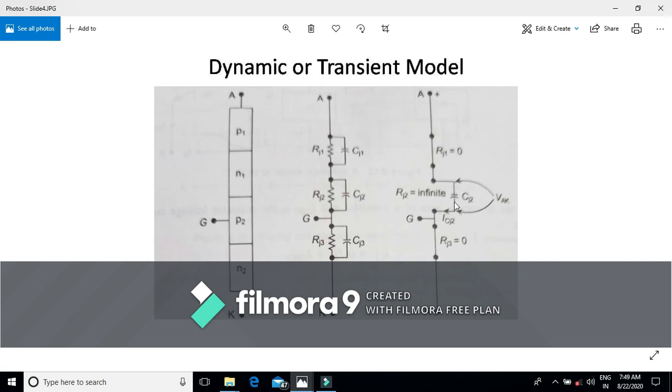If a rapidly rising anode to cathode voltage is applied across the anode cathode terminals, the magnitude of ICJ2 becomes very large. It reaches the gate layer P2 and, as it is very large due to a sudden rise in anode to cathode voltage, it behaves like the gate current.